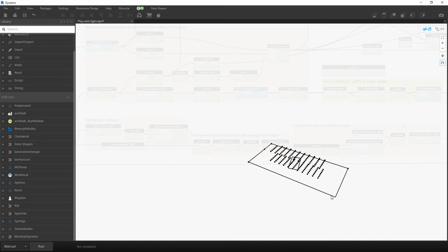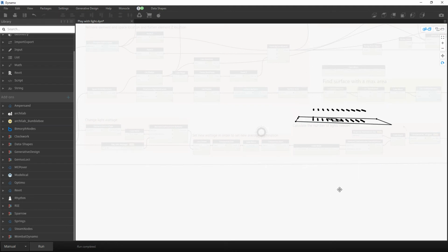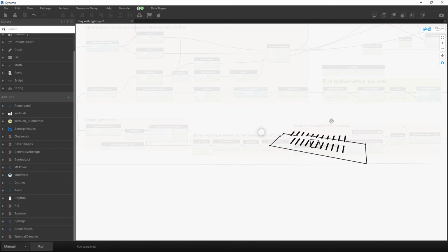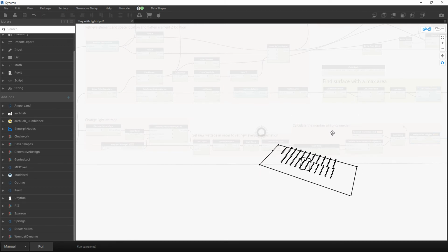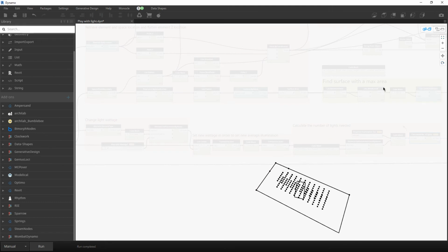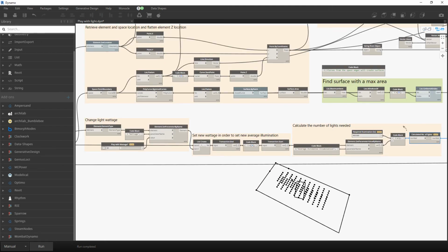If we take a look at this geometry, all your lighting fixtures are probably somewhere at the ceiling level, but in order to determine this length over here and this length over here, so basically from your chosen lighting fixtures to the space boundary, we need at first to flatten everything. So we will take our lighting fixtures and we will set that the height is at 0, so we can easily then determine the distance between the space boundary and the position of the light fixture. Then at some point we will again increase that height, but in order to calculate everything we need to flatten that.